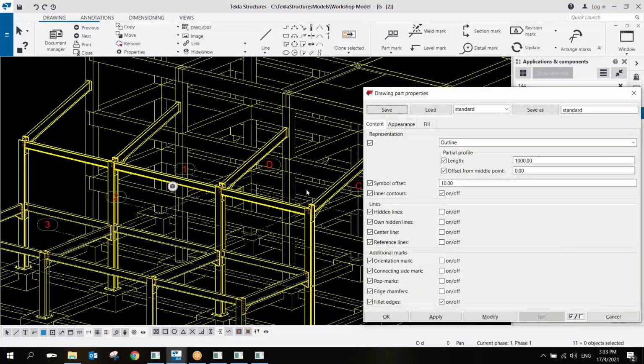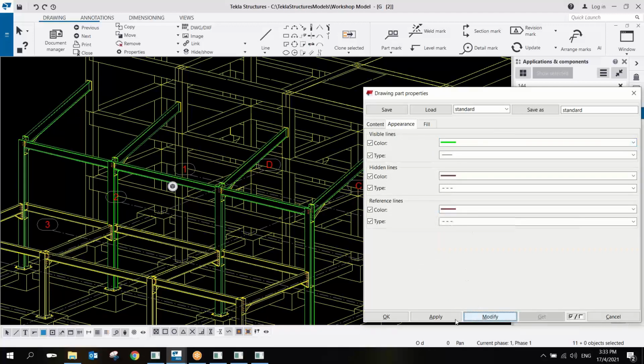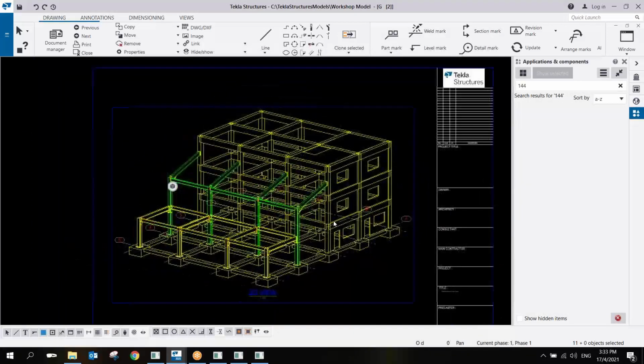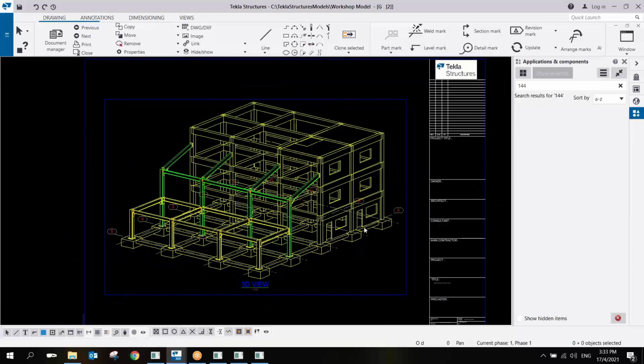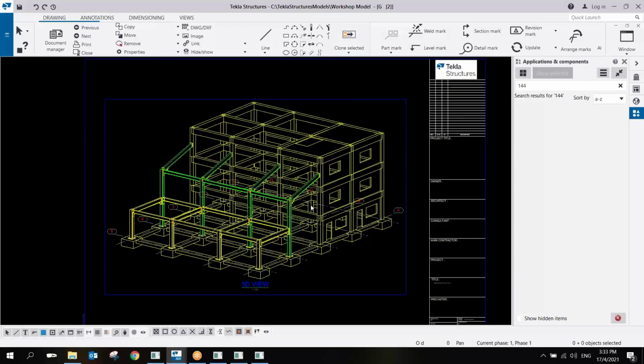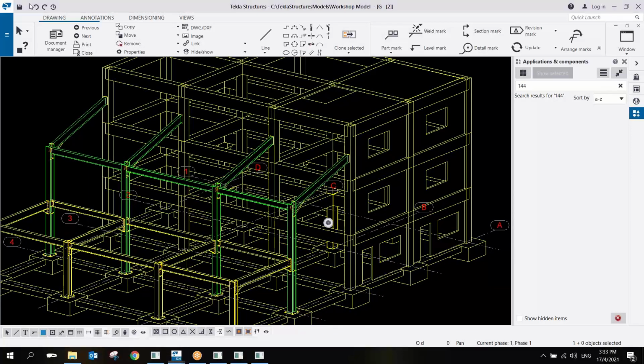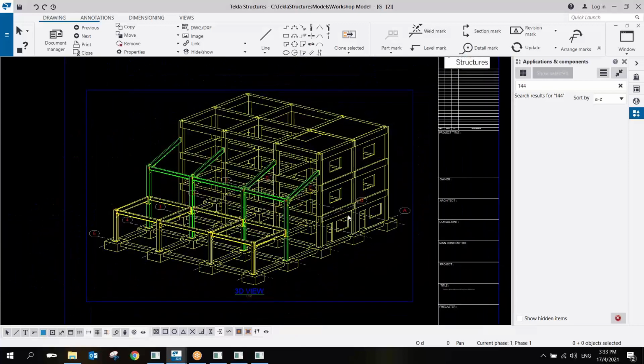And then here, I can select that one individually, and then you can change the color if you like. But of course, if you press B, it will be black and white only. But again, the color also deals with our pen assignment. Later, if we still have time, I can show you the print in PDF files.